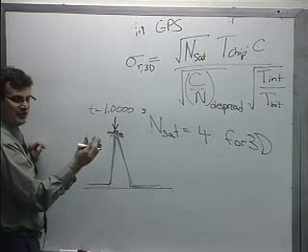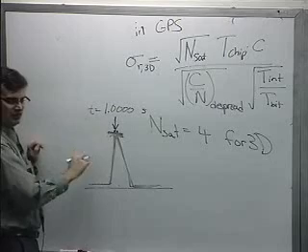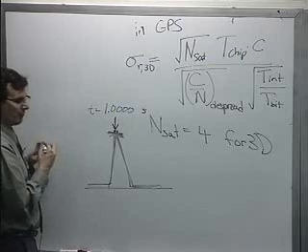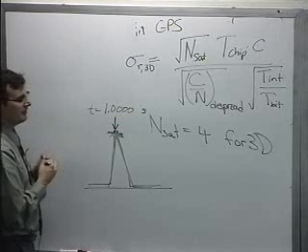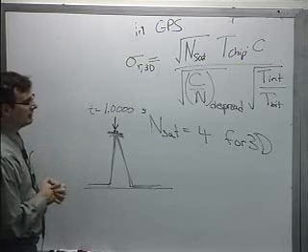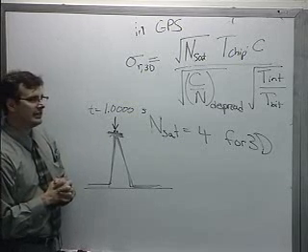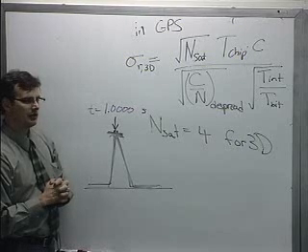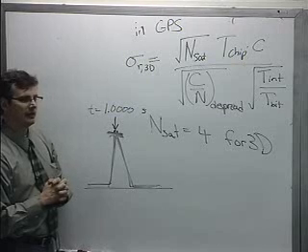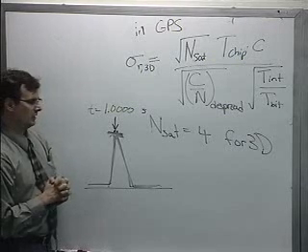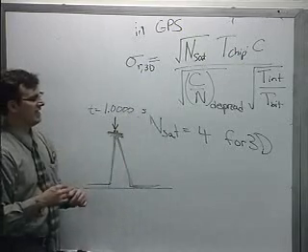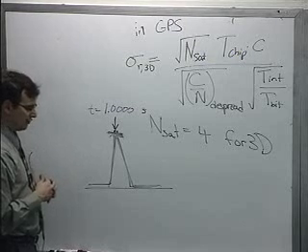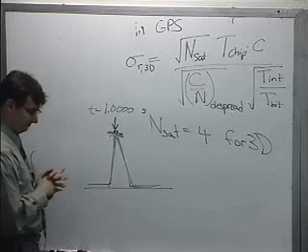So at high signal to noise ratio, 30 dB or higher, it's a beautiful algorithm to use. At low signal to noise ratio, less than 10 dB, you're almost back to your chip performance. Luckily, you usually get at least 20 to 30 dB, over 20 dB on a despread GPS waveform. So that means you can get a factor of at least 10 there, maybe higher. It depends on how good your receiver is. Any other questions?